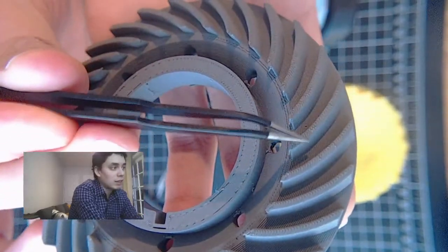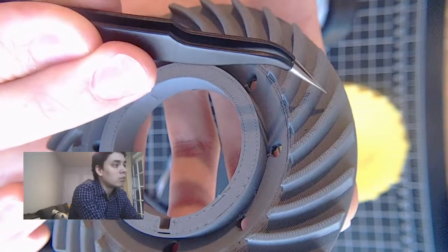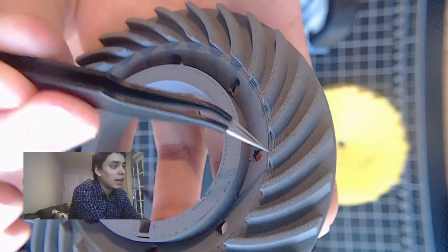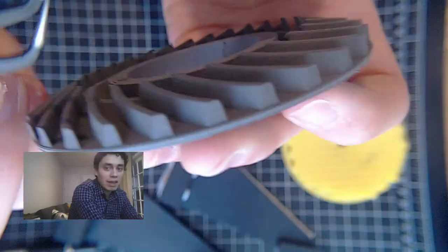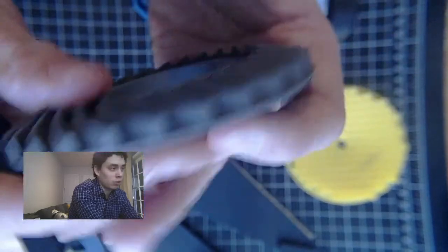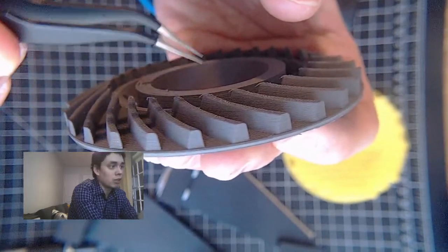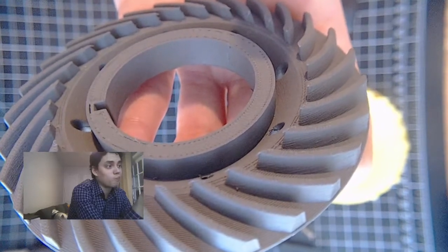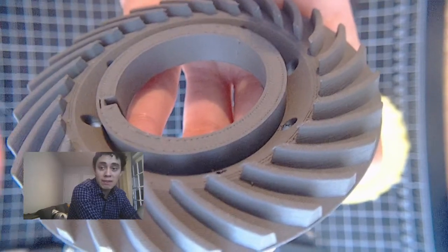If you see the layer lines here, we could count them. There's no more than, I would say, 20 or 30 layers describing this element. You can count them here because this angle is very shallow, almost flat. It's not completely flat, so if I look at it sideways, it does have a gradient, like this conical element coming from the base and flaring up to the top. But the shallower my geometry becomes, the fewer layers I'll have in order to describe that geometry.